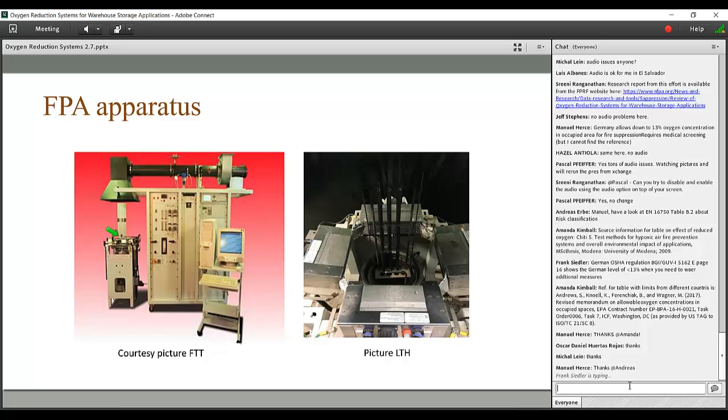You have a number of four heaters. I think maybe they are better to see here. That's one of them, which are also radiative heaters, which expose the sample which is in the middle. If you look at this, you see that there's a chimney, so that means that in the standard test setup from the FPA, the flow around the sample can be controlled from, let us say, 0 up to an oxygen concentration as high as you want.